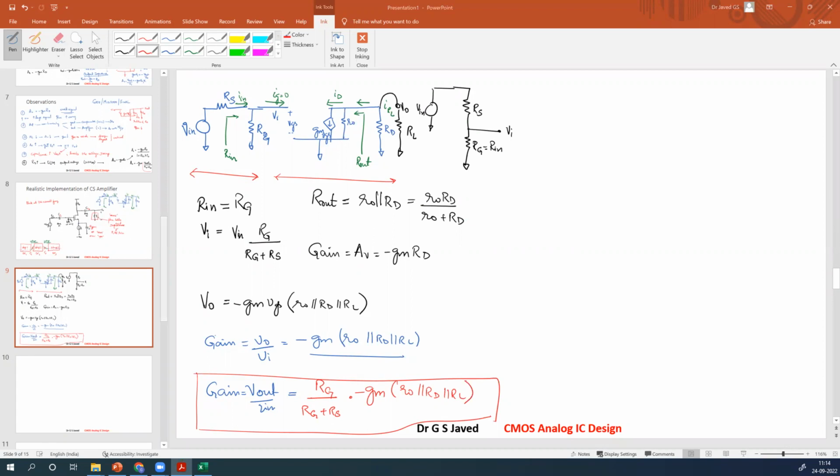Now, what happens when there is distortion? How do you introduce distortion here? Where are the ways you can introduce distortion? Distortion can happen when there is an extremely large signal coming. So what we can do, we will replace V in with this signal. If we make V in equal to 4 volts plus V in of t, add a DC voltage also.